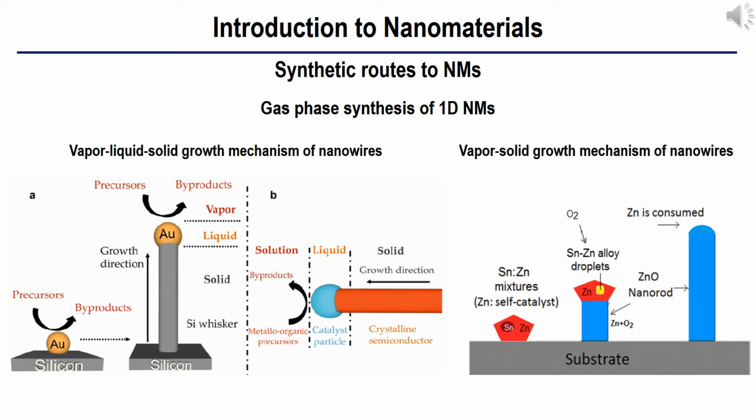For example, the growth of silicon nanowires is initiated with vapor transport of silicon precursors to catalytic metal nanoparticles such as gold spheres, as shown in the left figures. The transported precursors diffuse in the gold nanoparticles, forming a temporary alloy. However, the alloy is thermodynamically unstable since silicon molecules in the gold are supersaturated.